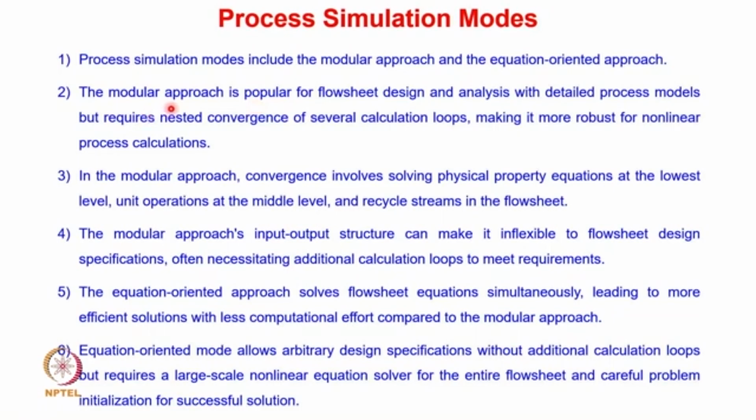Okay. The modular approach is popular for flowsheet design and analysis with detailed process models, but requires nested convergence of several calculation loops, making it more robust for non-linear process calculations. Clearly, if there are several non-linear equations with respect to individual units, approximating these non-linear equations using linear equations, as we have seen in the initial material energy balance session, is going to give you some error, isn't it?